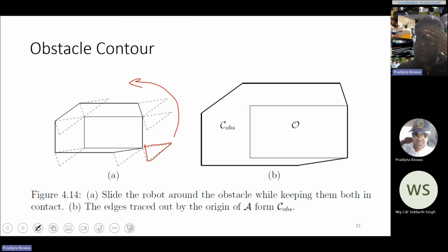So as long as I am outside that contour, I will know that the chair will not hit the table. Similar principle: you can see that we are basically dragging it along the surface. And since the robot cannot rotate, in this case I am dragging the robot along its edge. Here I am dragging the robot across the edge of the obstacle, but here I am dragging the robot across the robot's edge. And similarly, we bring it back to the starting point here.